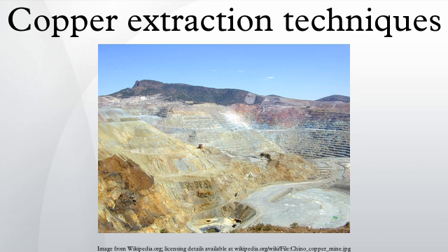The sulfur dioxide is captured for use in earlier leaching processes. Fire refining. The blister copper is put into an anode furnace, a furnace that refines the blister copper to anode-grade copper in 2 stages by removing most of the remaining sulfur and iron, and then removing oxygen introduced during the first stage. This second stage, often referred to as poling, is done by blowing natural gas, or some other reducing agent, through the molten copper oxide.